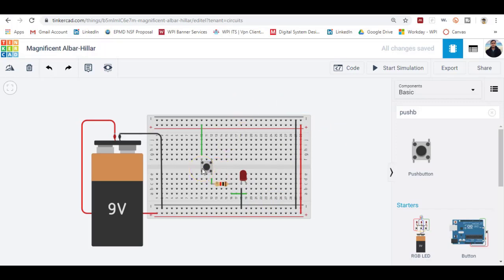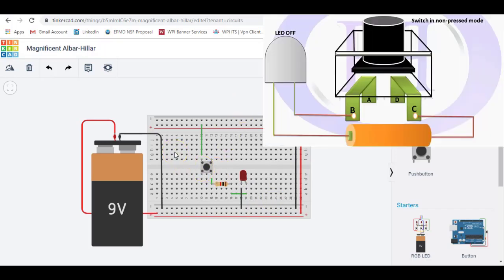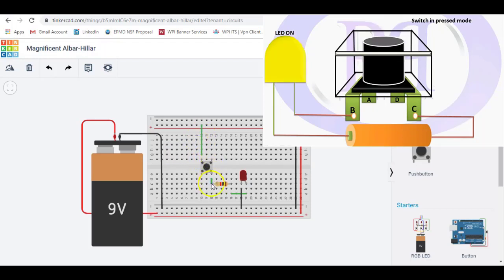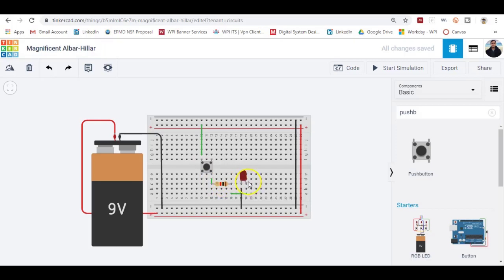Remember, a push button is a mechanical device, and the way it works, when the user presses the button, it actually just closes the contact. So metal contacts are then in touch, and then this 9 volt will go past the closed contact and then go past this resistor and then into the LED. The only purpose of using this resistor is we don't want to burn our LED because 9 volt is way too much. It only needs about 1.8 to 2 volts.